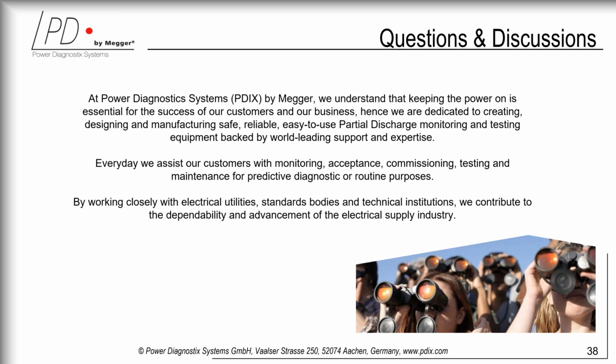Yeah, hello everyone. Good question. Alarm levels, warning levels, that's always the question when we commission such a system. We know from the factory acceptance test, a typical acceptance level for a power transformer, oil-filled power transformer, in a range of 100 to 200, 300 picocoulomb, and we try to achieve this sensitivity in the field.